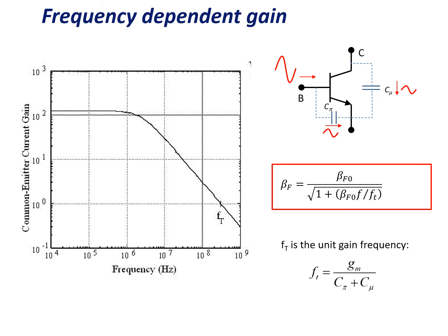These capacitances are there in every bipolar transistor, and what they cause is that the gain does depend on frequency. So as you get to a very high frequency, generally you will see the gain decrease. We usually define a concept called the unit gain frequency, FT. And FT actually relates directly to these two capacitances inside the device. These are important when we come to think about the high frequency operation of the transistor.